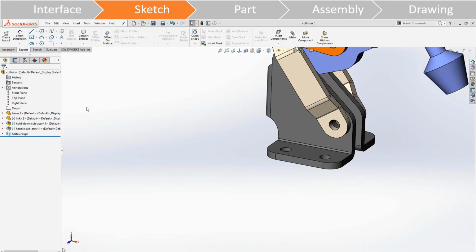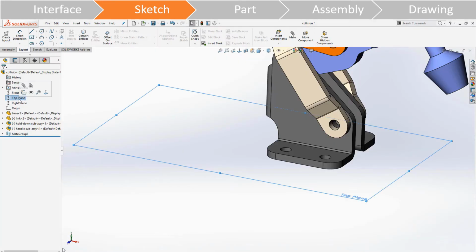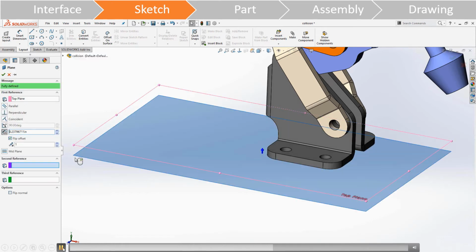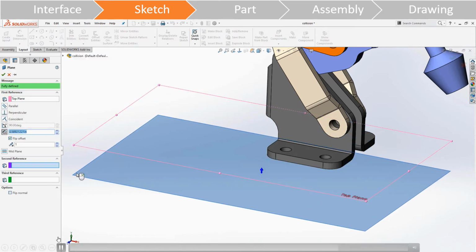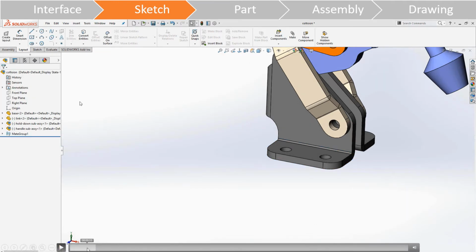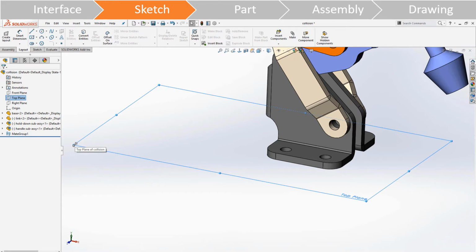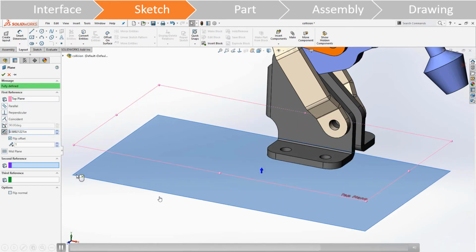When it comes to plane creation, again, a very simple thing. But sometimes people don't know that you can drag a brand new plane off of another plane very quickly by holding down your control button. So if you're just on the corner where you're getting one of those arrows, holding down control and your left mouse button, you can easily drag a new one right off of that, to whatever distance you want. You can start typing things straight from there.